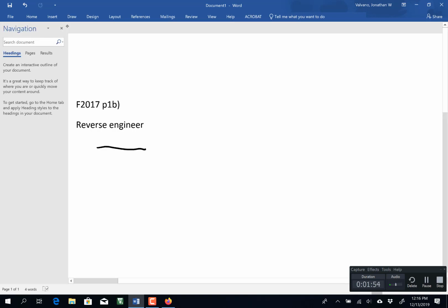All right, so the key to a reverse engineer is to know the 4 phases of a UART. It begins in idle phase, which is a high. If there's a separation between frames, it goes into an idle state. And then when it begins transmission, what's the next thing that can happen in a UART transmission? A start bit. It has to be a start bit. It can't be anything else.